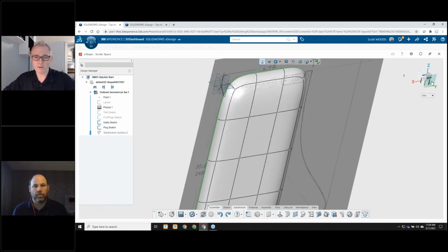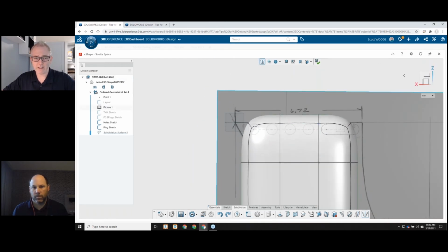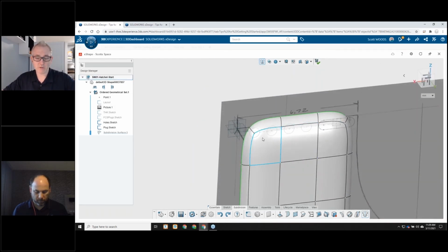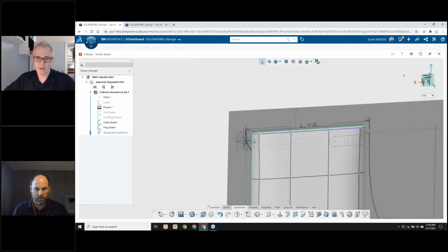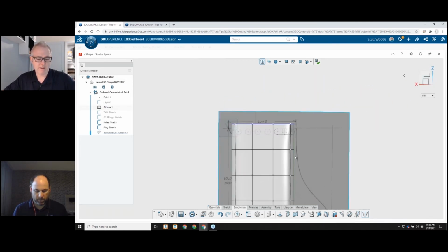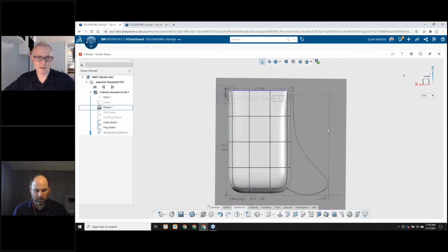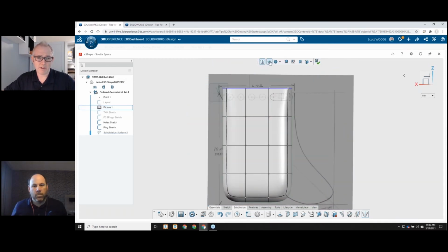So now what I'm going to do is flatten the top so I can attach it to the surfboard once I bring this into SOLIDWORKS. We've got a great tool here called Crease Edges. It does exactly what it sounds like it does. We can just crease those edges so I have a nice flat surface that I can mate to the bottom of that board within SOLIDWORKS. You know, cut some holes in here and create some fasteners and all that good stuff.